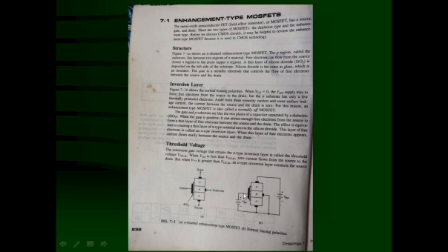So when the gate becomes positive, VGS is connected here, the battery. Because of this, this electrode is positive and this electrode, the substrate, is negative. So this will act as a capacitor between two conductors. There is an insulator, and just on this side of the SiO2, negative electrons are deposited, forming a thin layer of N-type material, which provides the path between source and drain.